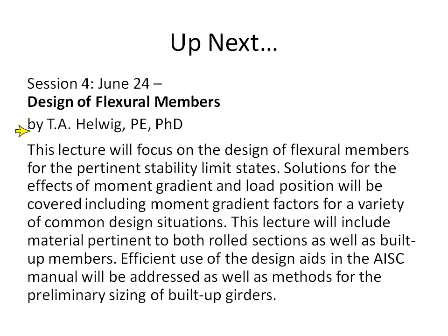Certainly, all of the work we did was assuming that the load was very close to the centroid. But if the load was on a post that was well above the centroid, there could be an overturning effect produced by that load being so far away from the neutral axis. We tend to call it a C sub B factor. Technically, the C sub B factor is for moment gradient, but purely speaking, if the C sub B factor is for moment gradient only, it can't be less than 1. But if you're going to let it go and account for other things like load placement along the height, then I suppose it could be.